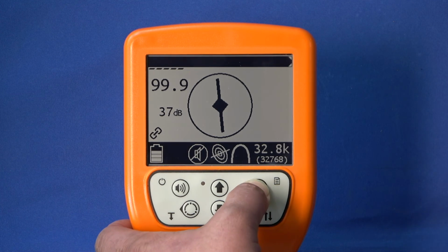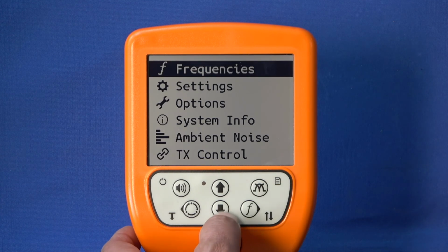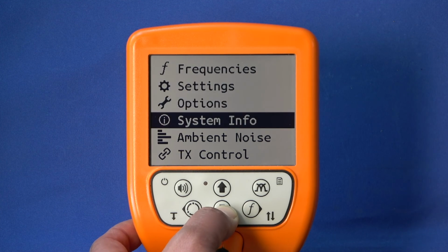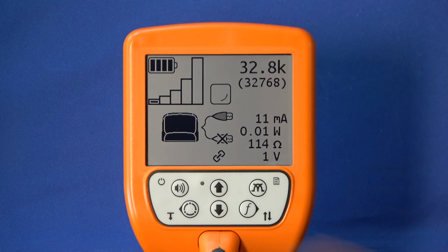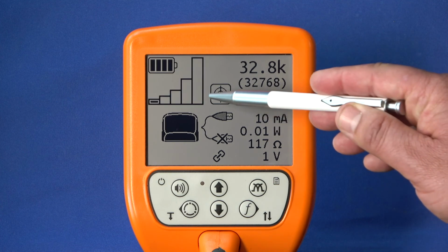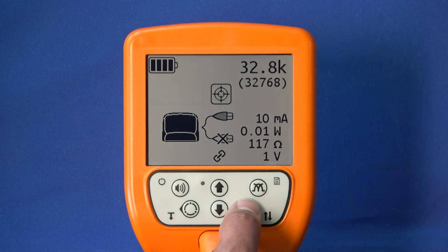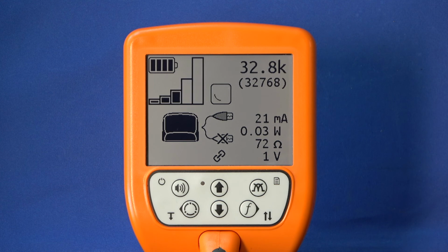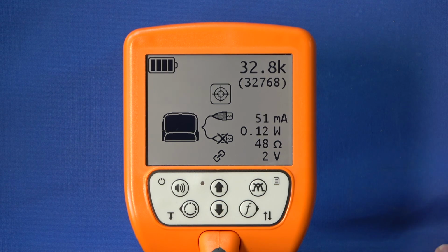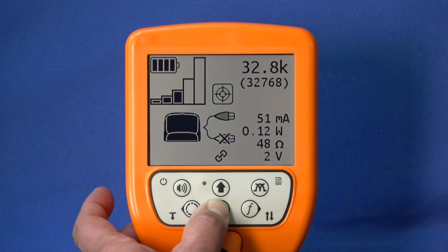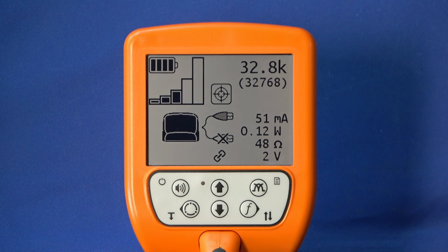For further setting options of the generator via the receiver, select the TX Control submenu in the Device menu. The display of the generator is now shown on the display of the receiver. The bar display of the output power is flashing. You can increase the output power of the generator by pressing the frequency key on the receiver. Use the down arrow key on the receiver to switch to the output of the generator.